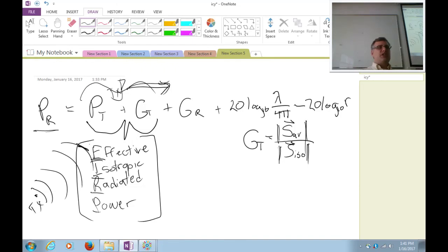Where the analogy tends to fall apart is, truthfully, antennas don't cast sharp shadows. The way I'm presenting it here, it sounds like I've got an electromagnetic aperture that's a cookie cutter, maybe circle shaped, and it sucks a circular amount of power out of the plane wave and converts that. And then you think, if I got behind that antenna, I should see a perfect disk cut out of the plane wave. Well, first of all, Maxwell's equations don't like sharp corners in the field solution.